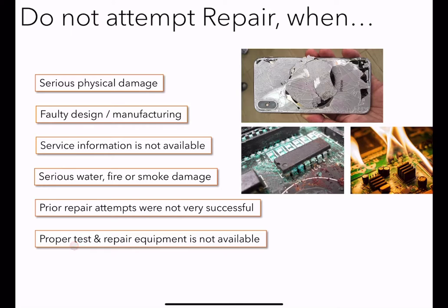means how much voltage is where and which component is working fine, which joint is okay and which wiring is fine. You cannot make those tests. And if you have proper testing equipment and you have tested it fine, but you do not have proper repair equipment, you should not attempt a repair, because if you do so, instead of repairing, you may cause some more faults.